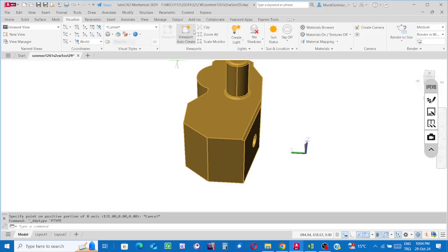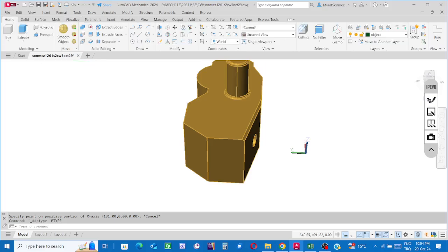Since these are to construct the oblique surface, to create the oblique surface in the end, it is, generally speaking, a construction stage. So, from the list of the transparent papers, well, select not object layer but construction layer. Okay, and then mark the points.